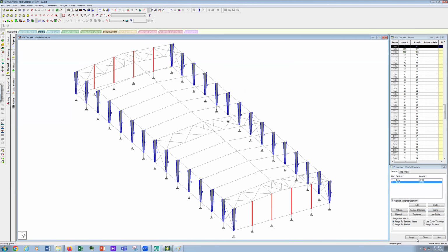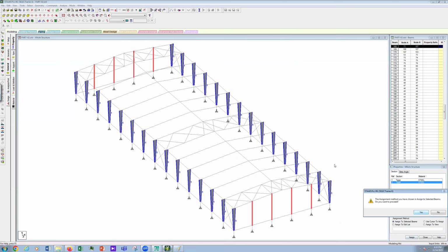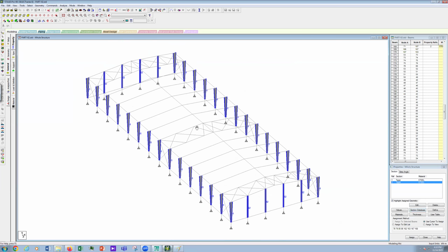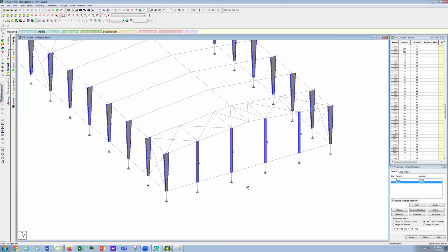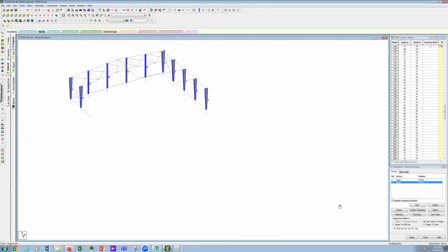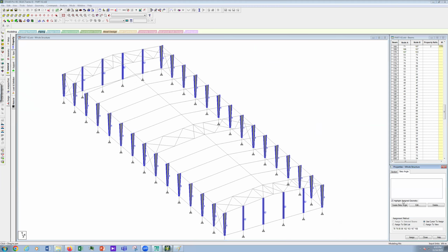You can rotate this section. How to rotate? Go to beta angle here and create beta angle. Just put 90 degrees here, and okay. Then select this beta 90, and then select this material too, with control and select.